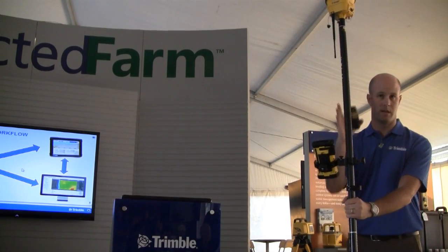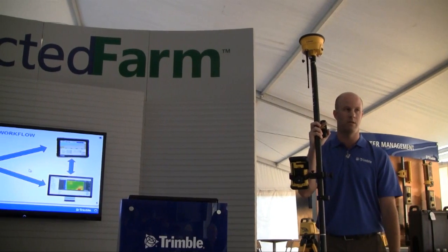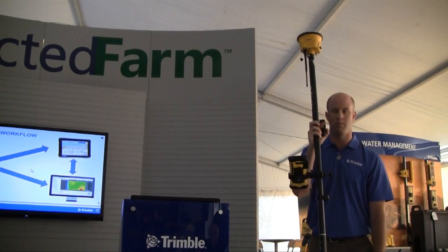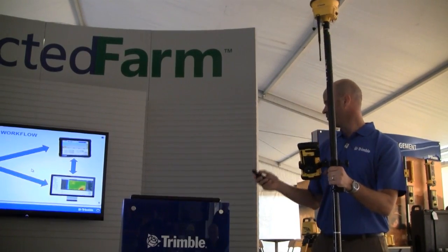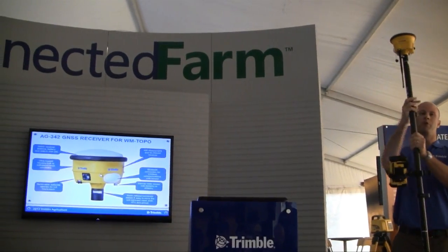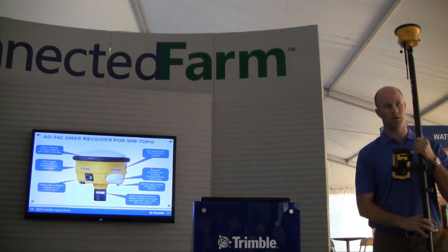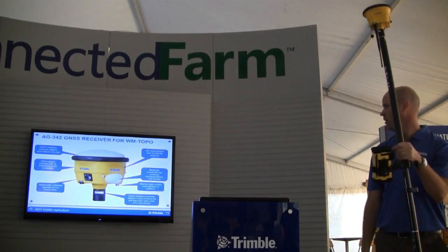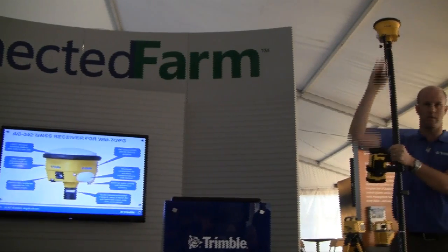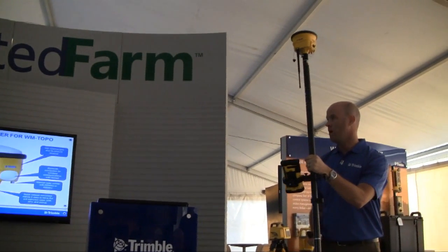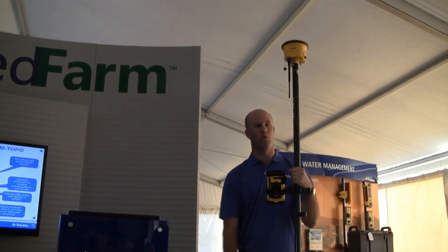And if you look outside, you see a lot of water management machines. That is what I'm talking about. We can control all those machines with 3D GPS to put in either drainage tile or to land level our field. So the receiver itself, this is a brand new receiver for Trimble. It's a 440 channel GPS GLONASS receiver, fully ruggedized. This thing is pretty difficult to break. It's really tough. It includes the antenna, the receiver, the battery, and the radio all in one unit.